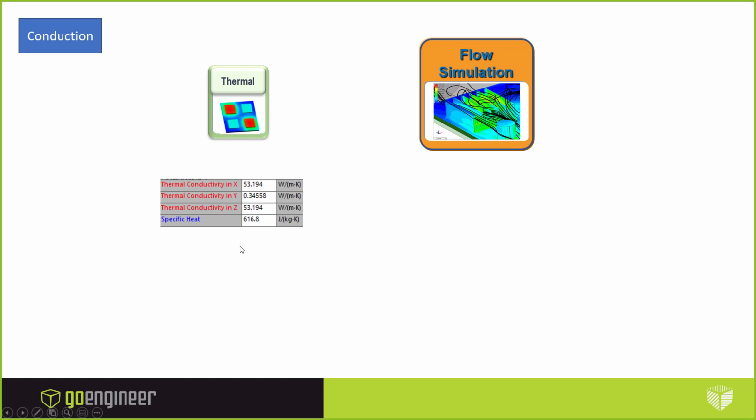Now in the case of a PCB, it's going to have an orthotropic conductivity. So we'll have to model in a conductivity in the X direction, a different one in the Y, this is going through the plane of the board, and then maybe a similar one in the Z. We'll have to approximate that entire PCB body perhaps as an orthotropic material. That's one way to model it.